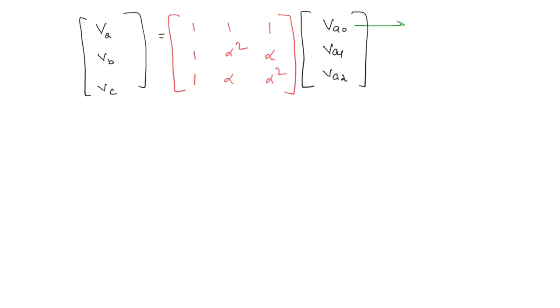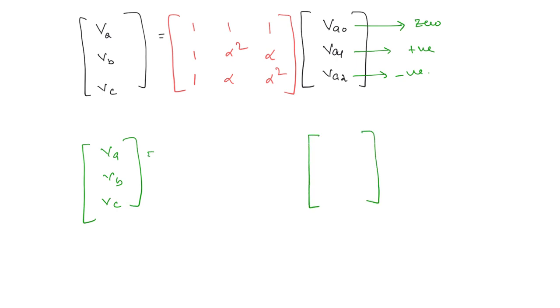So remember here the first component that you have is the zero sequence component, and then you have positive and negative sequence. Okay. Now what if you are writing VA, VB and VC as it is, but this you are first expressing the positive sequence component, that is VA1, right? And next you have VA2. Next finally you have zero sequence component. Okay. So you can see the first one here is the positive sequence, here this is negative sequence, and this is the zero sequence. In this case what will be the matrix? A matrix, right? This is A.